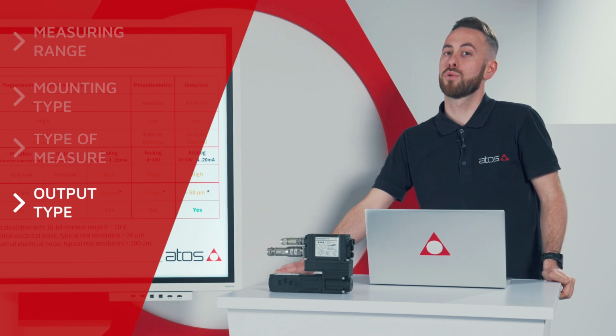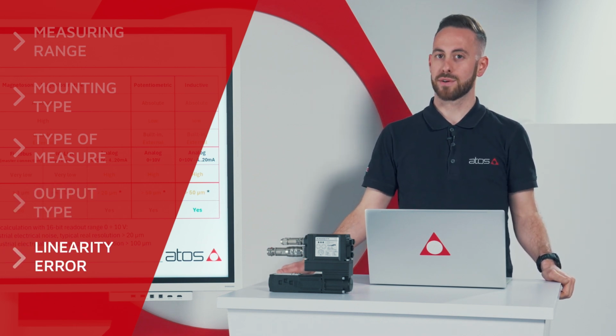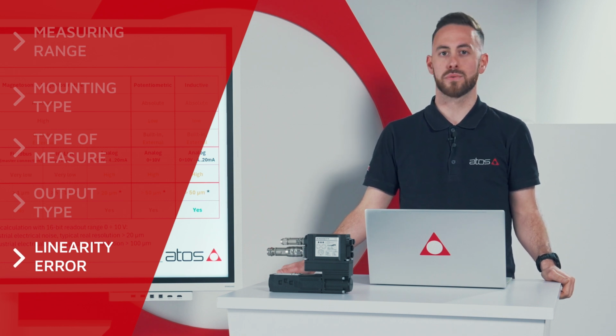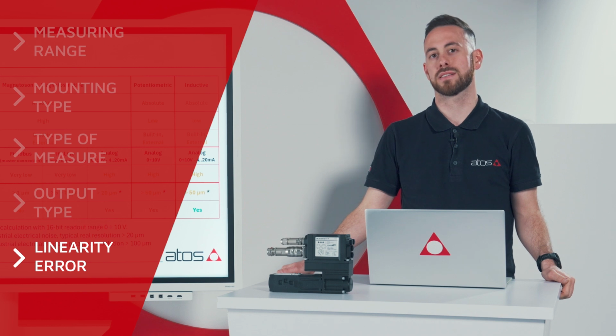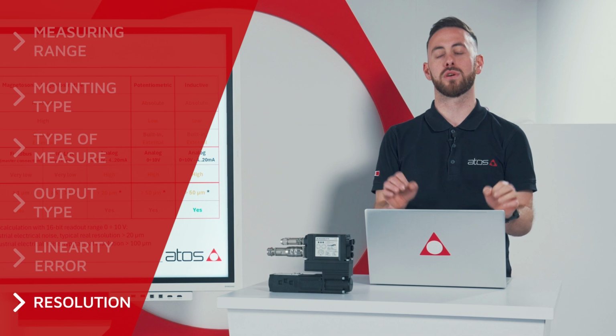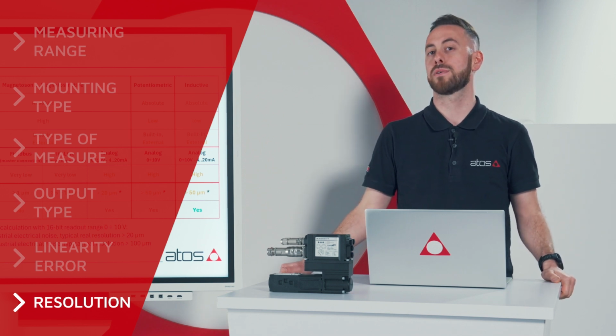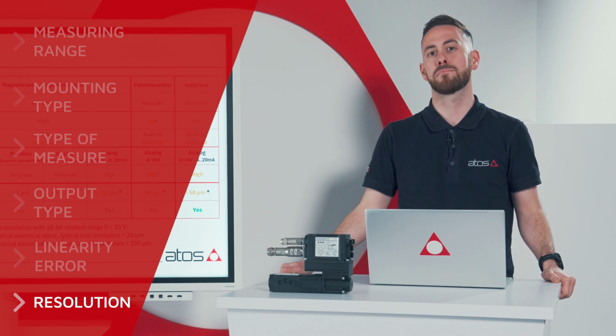Other very important parameters of a position transducer are the linearity error, intended as the difference between the ideal and the real response measured by the device, and the resolution, intended as the minimum variation in quantity that our device is able to detect, a very important parameter to define accuracy and repeatability of the positioning system.